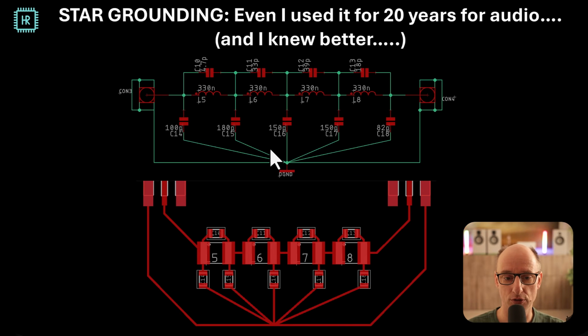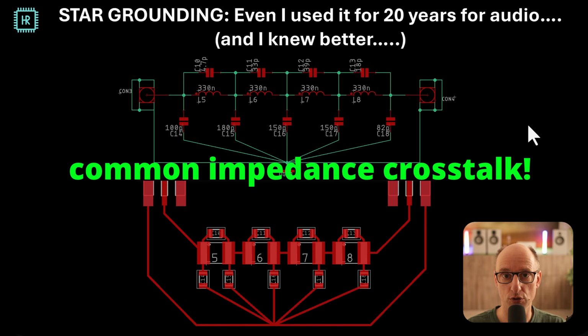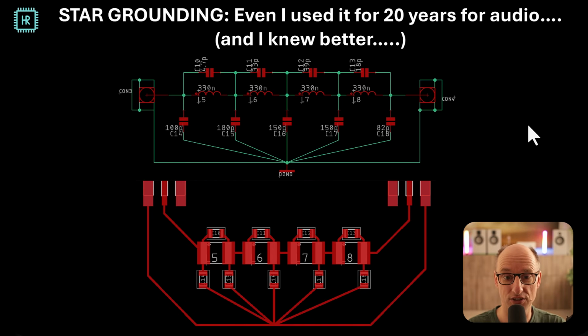Now it has a number of ground connections, and the whole idea of star grounding, you can already see it here. This looks like a star. Each ground connection has its own wire to the central grounding point. And this is a lot like my rule number 2 for good grounding: give each ground connection its own via. The advantage is you have no crosstalk. The big disadvantage is the way it's done here with traces instead of a ground plane, it only works for DC. So let's have a look what happens when we compare it to the ideal competitor, a real ground plane.